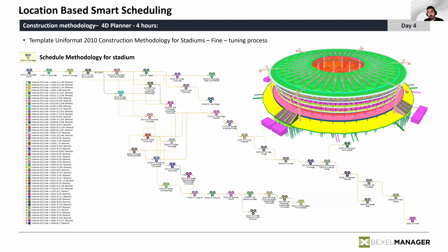What we also had to do prior to that is populate the cost classification codes, because another important thing is we had to quantify the works for the project properly. So we had to get the quantities and descriptions from the model for all the works that have to be executed. For this specific project, we used a combination of UniFormat and MasterFormat cost classifications. Of course, the system is completely open and you can use any cost classification in the world. But in this case, we were able to quickly populate the codes using the data enrichment method.